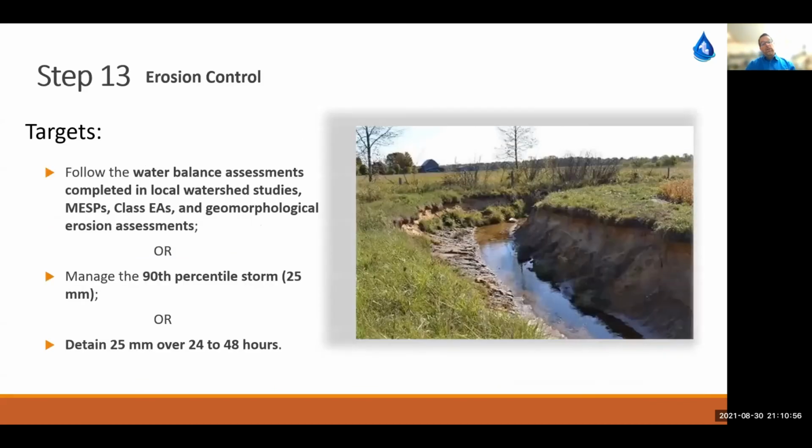So, continuing on to erosion. I mentioned before that stormwater management only achieves a certain amount of infiltration, at least it meets the pre-development conditions. Evapotranspiration, we cannot meet the pre-development levels. So we have to meet the erosion control requirements downstream with the additional runoff that is produced from the site, even after the on-site controls are implemented.